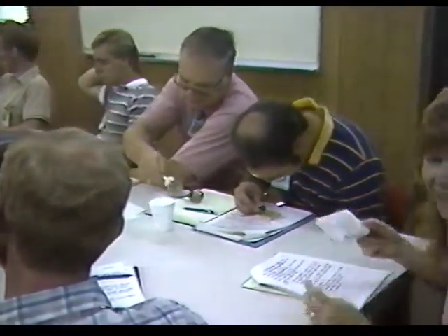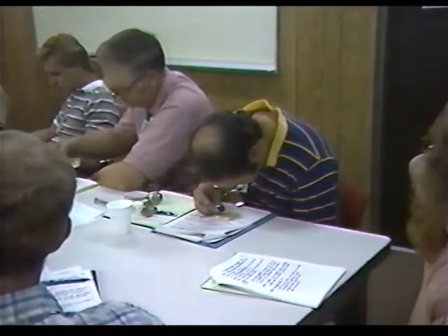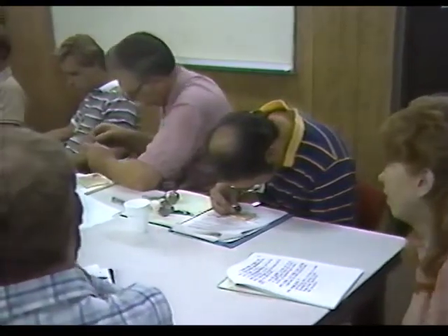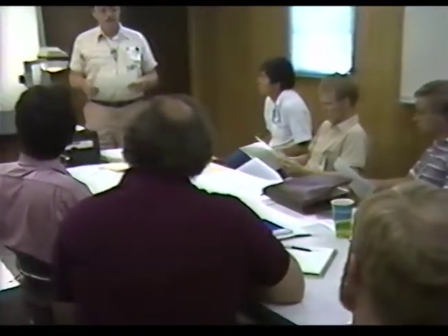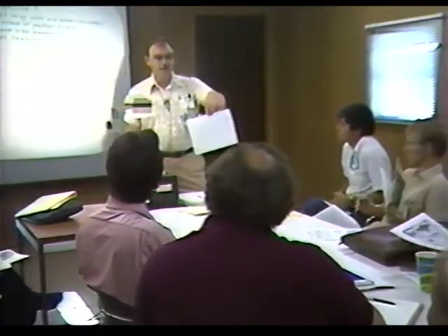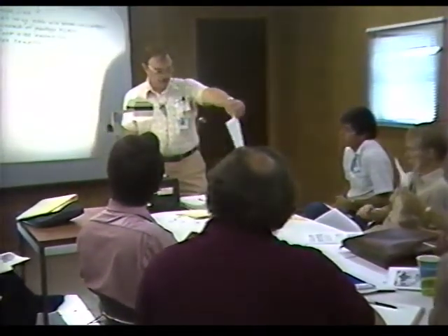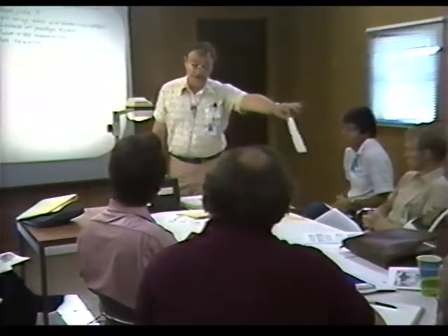If you can't really see that beam-leaded part, here's a picture of one. And since we didn't cover much on that, Al and Gary ginned up this morning a plot on the HP parameter analyzer of a forward on a silicon device for you to stare at, and you'll see the oft-quoted 0.7 of a volt turn-on on that current scale.